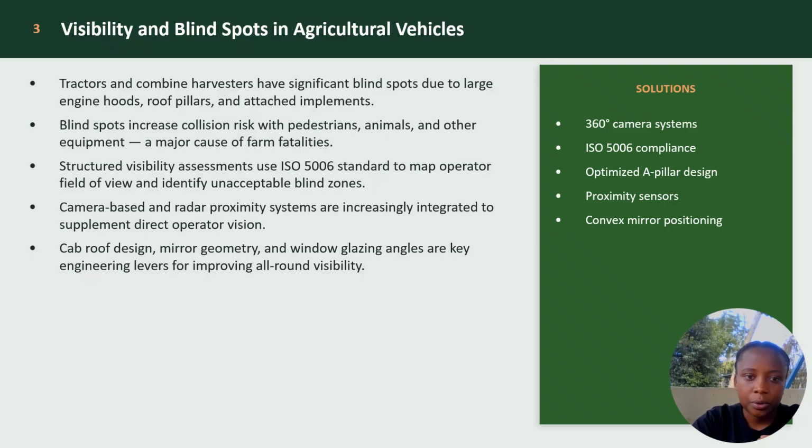The second one, blind spots increase the collision risk with pedestrians, animals, and other equipment, a major cause of farm fatalities. The third one, structural visibility assessment uses the international standard ISO 5006 to map the operator field of view and identify unacceptable blind zones. The fourth one, camera-based and radar proximity systems are integrated to supplement direct operator vision.